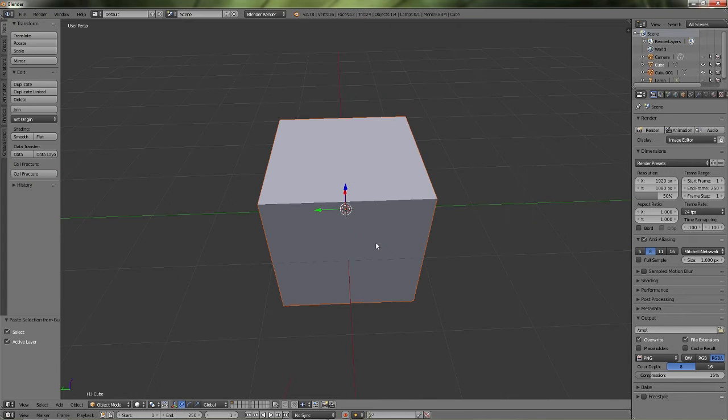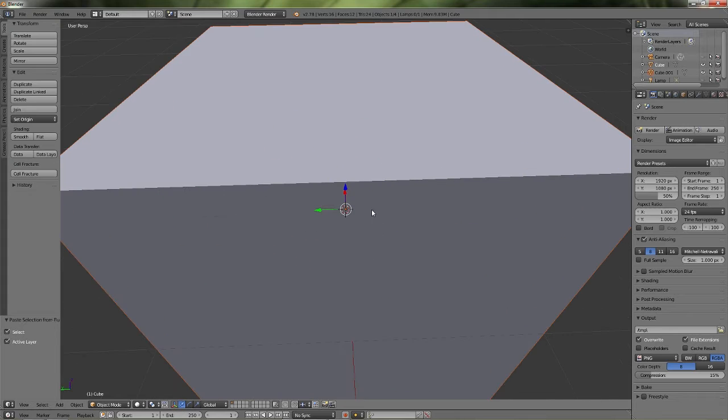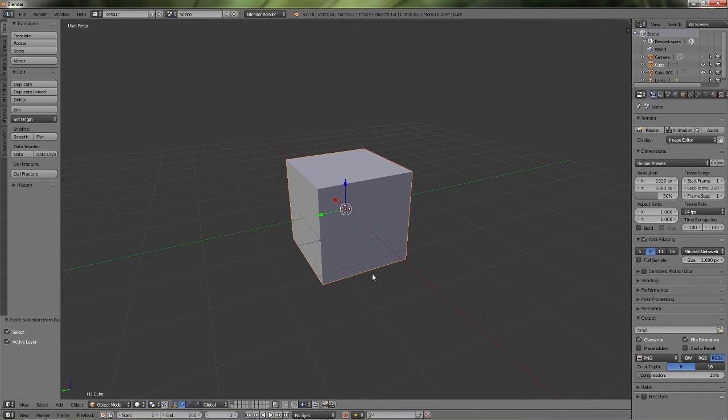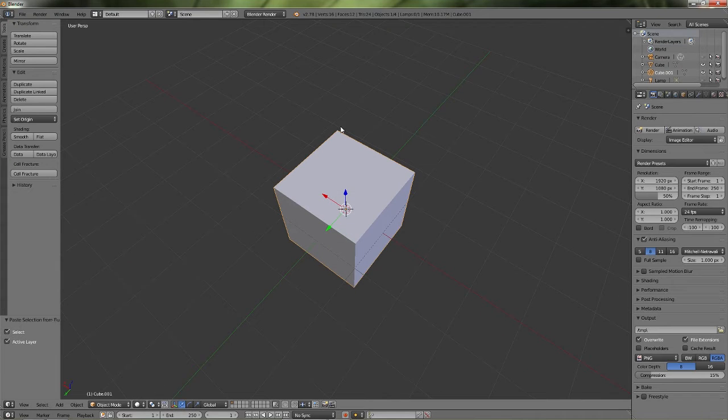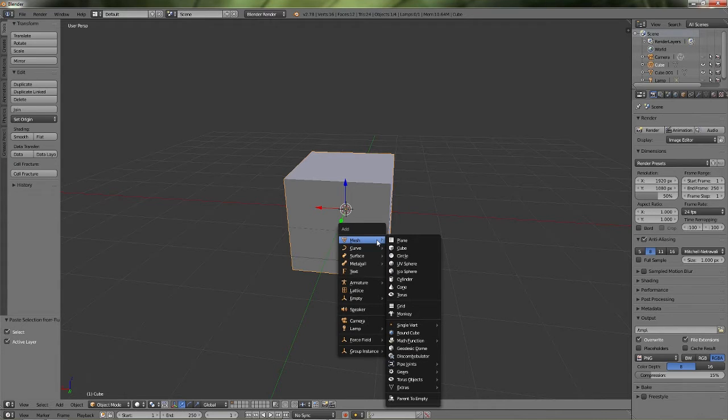If you need to ever put that back because you left click somewhere, you can hit Shift C and it will go back for you. To actually select something, you'll notice that the orange box will come up on what's selected, but you will just right click on the object that you want to select.